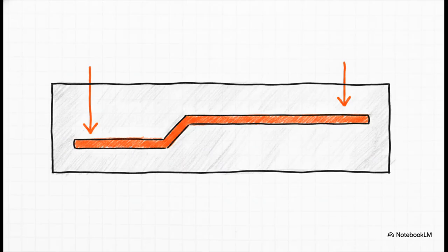And what about a one-way slab? Well, alternate bottom bars are cranked near the supports, which requires a very specific diagonal addition. See, the crank rises through the available depth of the slab, going from the bottom cover up to the top cover. This diagonal portion actually adds length to the bar. To account for this mathematically, you use a constant of 0.42 times the effective depth of the crank. And yep, you just plug that addition right back into your master formula.